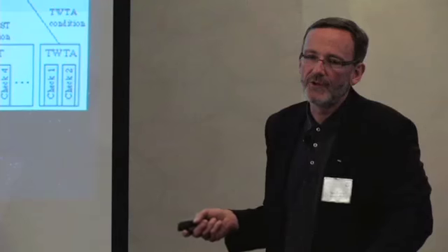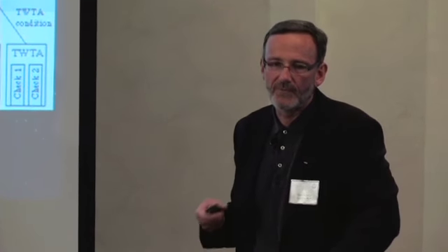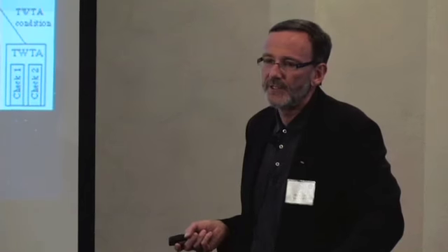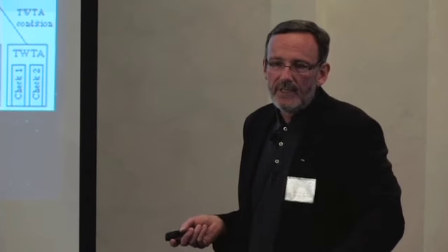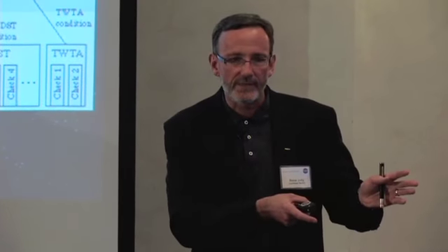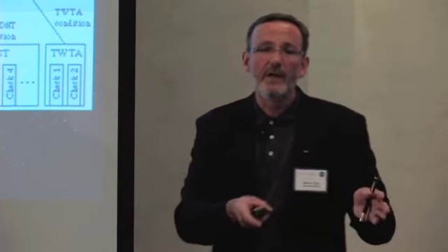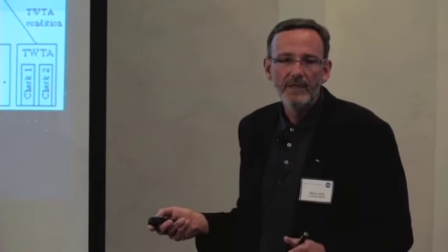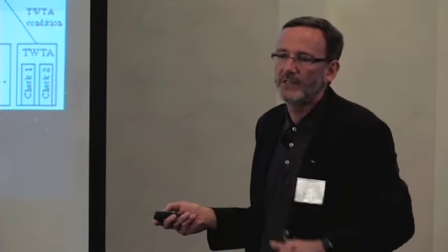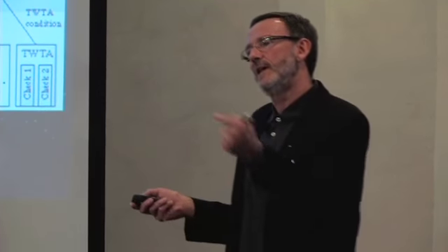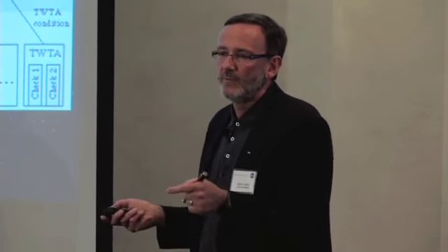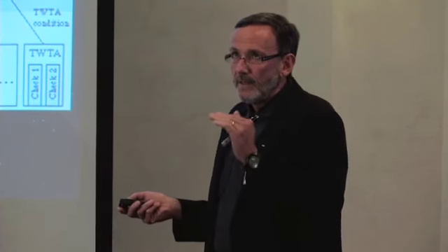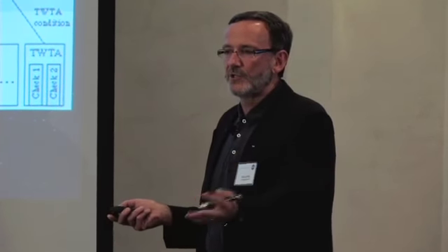So one of the things I wanted you to think about in the design of your mission, and certainly I am for GOES-R and for others, is maximally dissimilar safe hold. That is something that might even be old school, like closing the sun sensor around an analog device, which has been done. We have lots of examples of that in past design. But you need to think about that, because claiming that you're okay just because you have redundancy may not be the case anymore, because the game is changing on you. One of the things I didn't point out is we don't push the electronics design anymore. We actually receive it from the commercial industry, right? We upgrade parts.